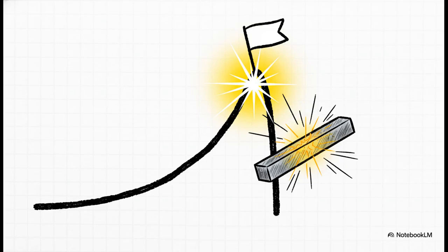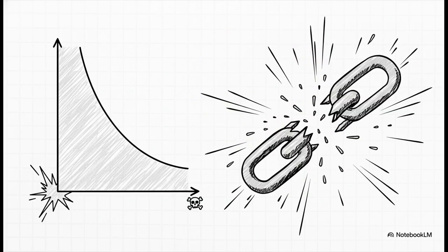As we keep applying more and more stress, we climb all the way to the very top of the curve. This peak is called the ultimate strength point. This is the absolute maximum stress the material can possibly handle. It's the material's moment of glory, you could say, holding on with everything it's got before it starts to fail. And finally, we reach the end of the story, the fracture point. After hitting its peak strength, the material actually starts to get weaker, and then, snap, it breaks. The story is over. The material has completely failed.